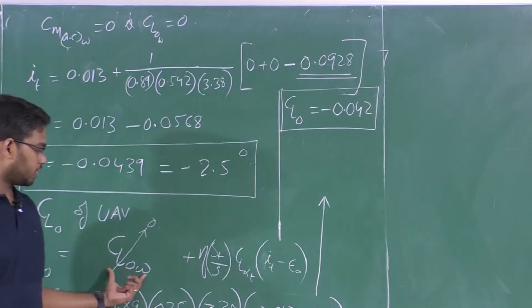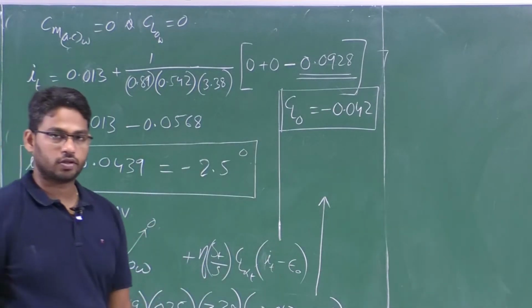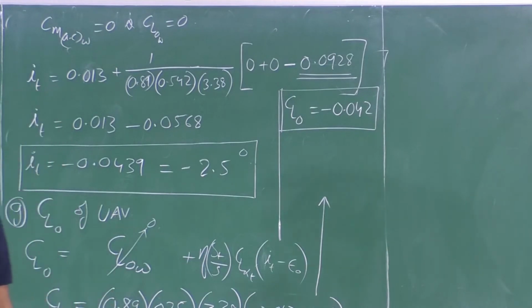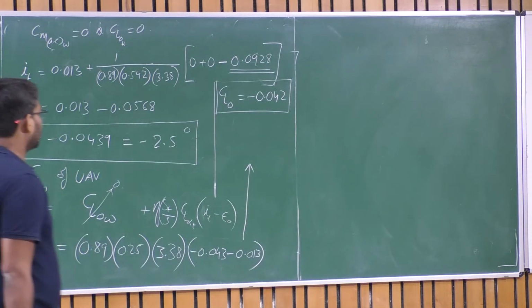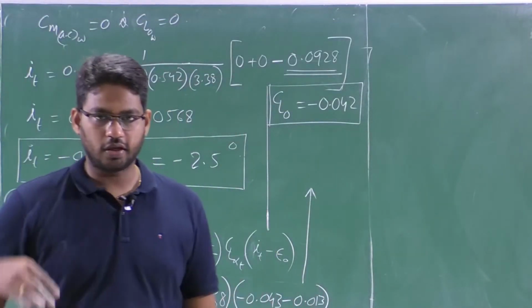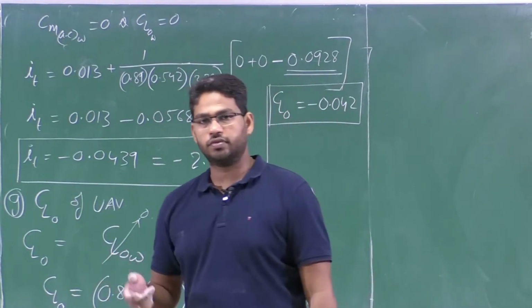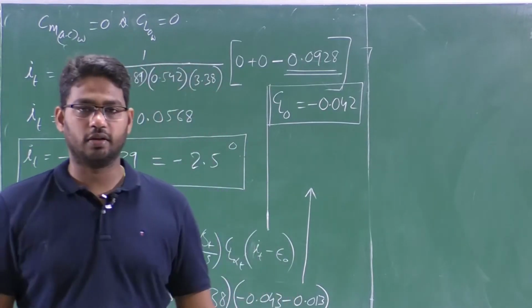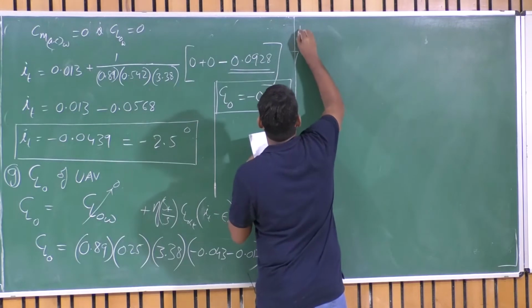So when the wing is symmetric, at 0 angle of attack you have negative lift. If you have a minus 2 degrees tail setting angle, you may not be able to fly at 0 angle of attack, since we have a symmetric wing there. So you need to trim always at a certain positive angle of attack, or employ a wing setting angle. When you consider a symmetric airfoil for the wing, then you have to maintain a wing setting angle. And let's take up the final question.